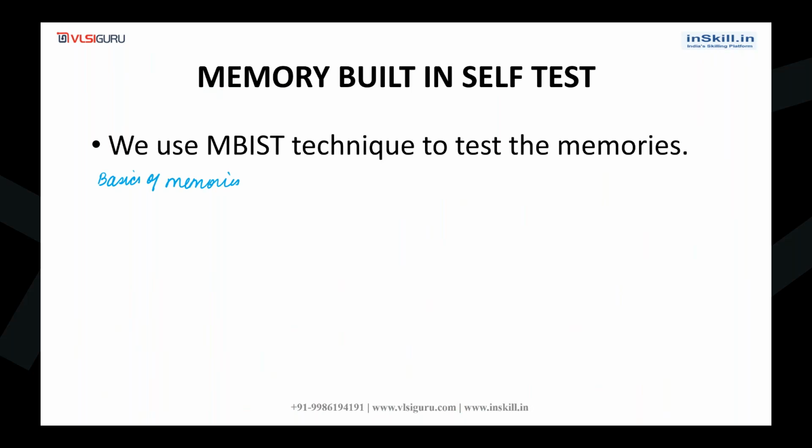Then we will go ahead with the topics required for a DFT engineer, which is the memory fault models. There will be various fault models like the stuck at fault model, transition fault model, address decoder fault, and coupling fault. We'll be covering those fault models.